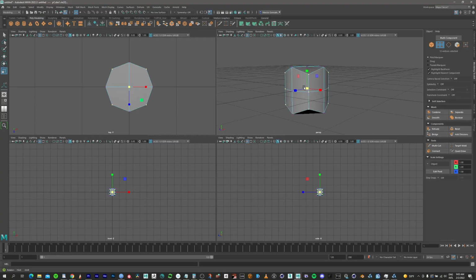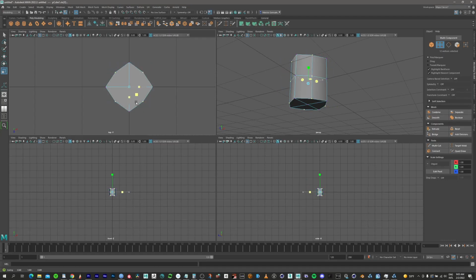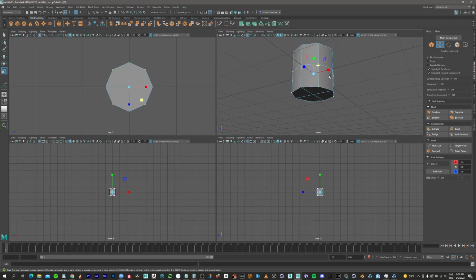If I scale everything, I'm not gonna get a flat top here, and that's not what I want. So let's scale, selecting this guy here, the green square, which means I'm gonna be scaling only on the blue and the red axis. So let's do this, and let's scale around here, looking good. It's gonna be like the center of our sword here.